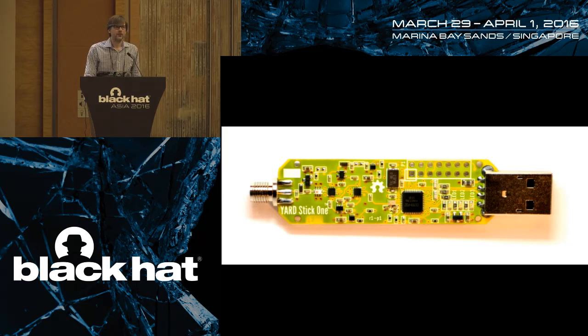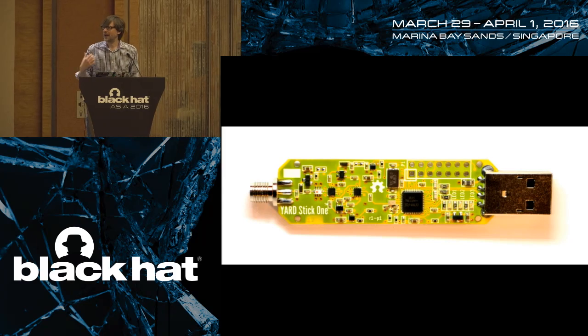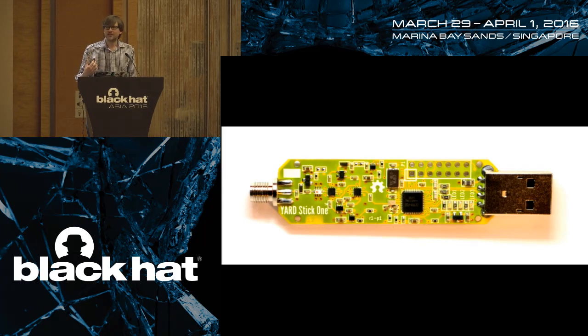I don't think the one I'm reversing today has a CC1111, but it has another chip that is kind of similar to the CC1111. The CC1111 is almost the same chip that's in my favorite pink toy, the IM-Me. That actually has a CC1110. This CC1111 is the exact same radio, exact same microcontroller. The only difference is that it adds a USB interface. So I'm able to make a little dongle out of it that gives my host computer a radio interface via USB.